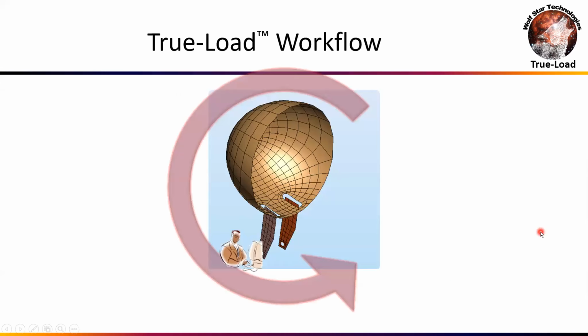All right, I'm going to go through the workflow one more time, this time with a little bit of graphics behind it. This is our training example we use in our training. It's a very nice example. This is a headlamp on a motorcycle. The analyst looks at this headlamp and says, this headlamp's attached to the handlebars, and it's getting input from the handlebars, from the front suspension, from the frame and engine vibrations. So he says, this problem is basically a base excitation problem.